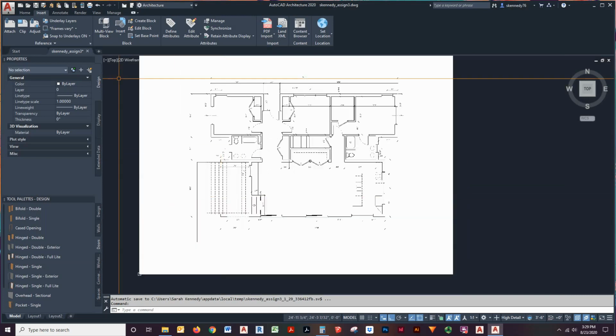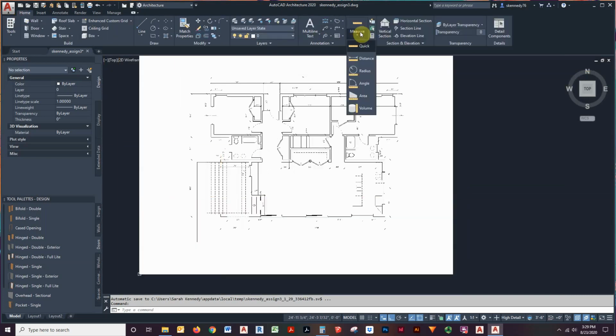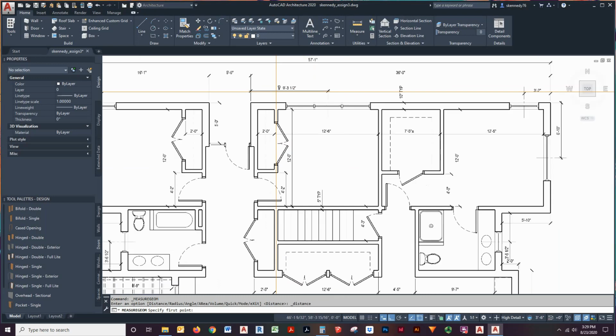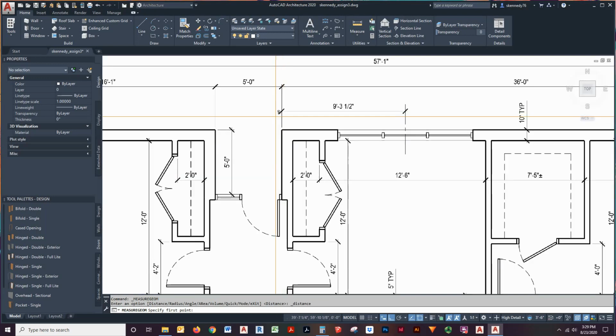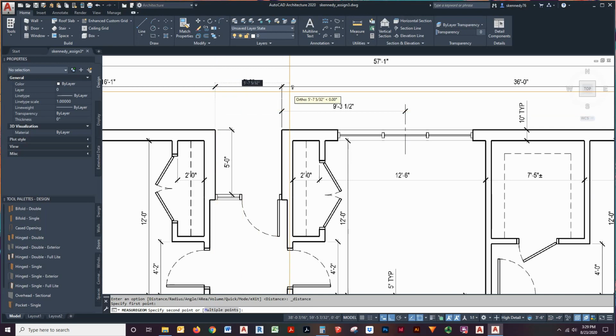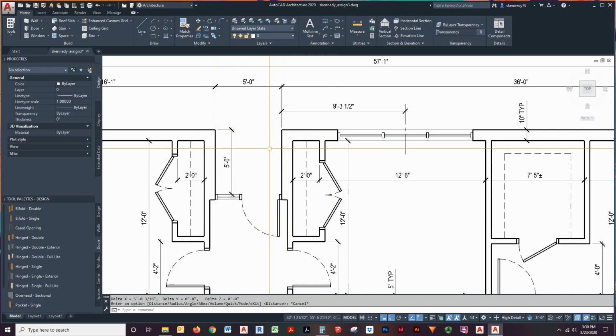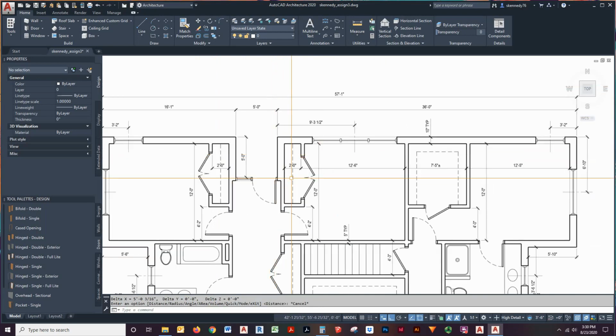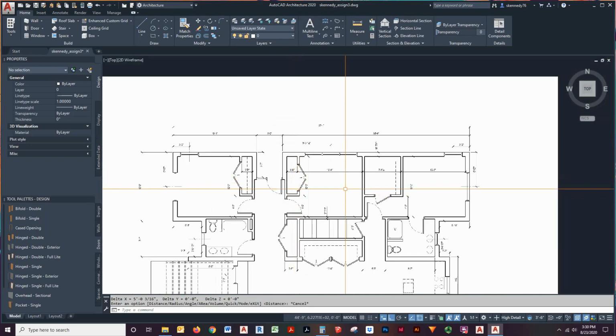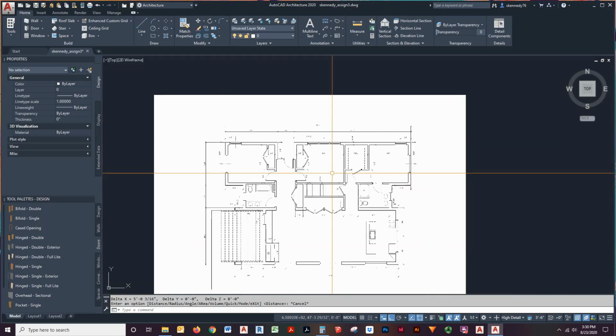So this one, if I go to home and then click distance, it should have come in at the correct scale. See how it blanked out, but it's still there. If I click here and then click here, it's giving me a readout of 5 foot, and that's just because I had to eyeball it. So I know that this properly scaled at the 48 scale factor, which is the scale the drawing should be brought into so that it's 1-to-1, real size.